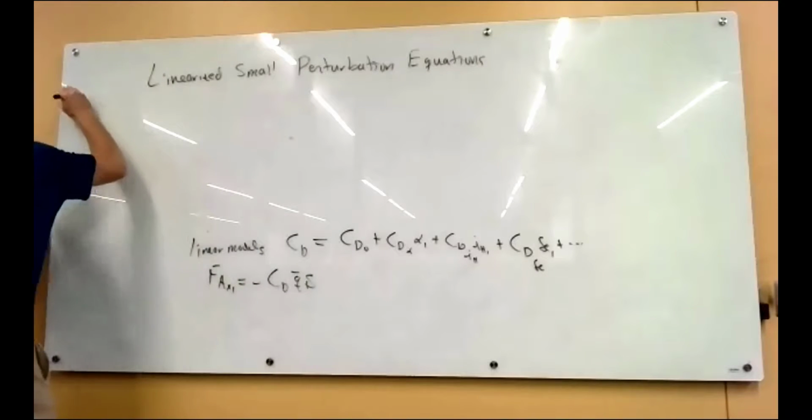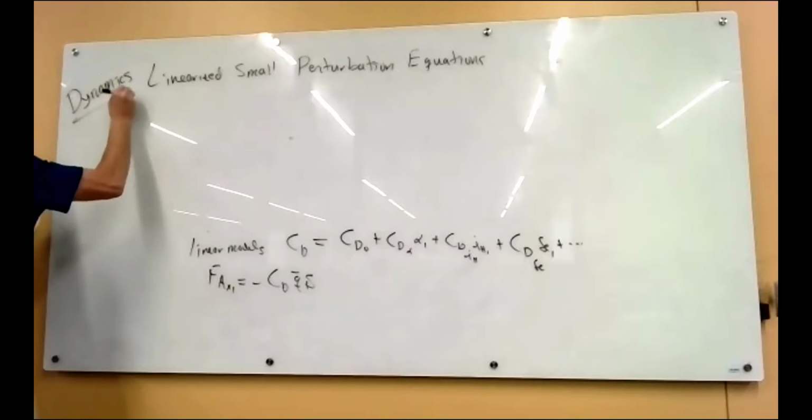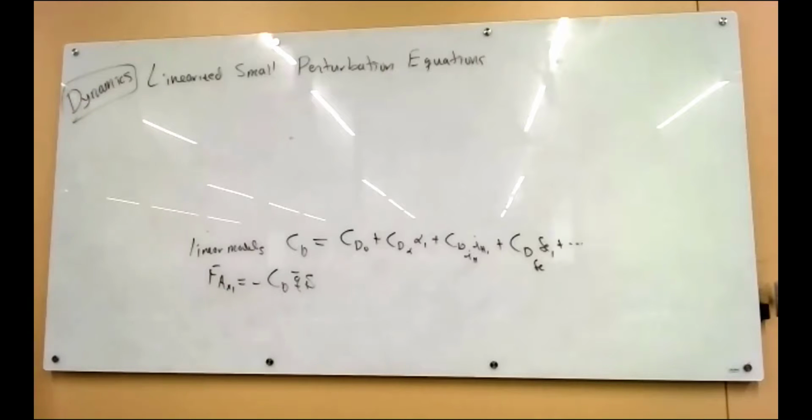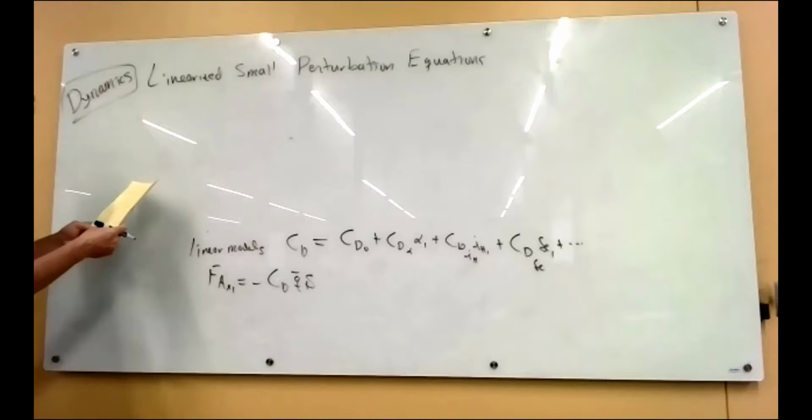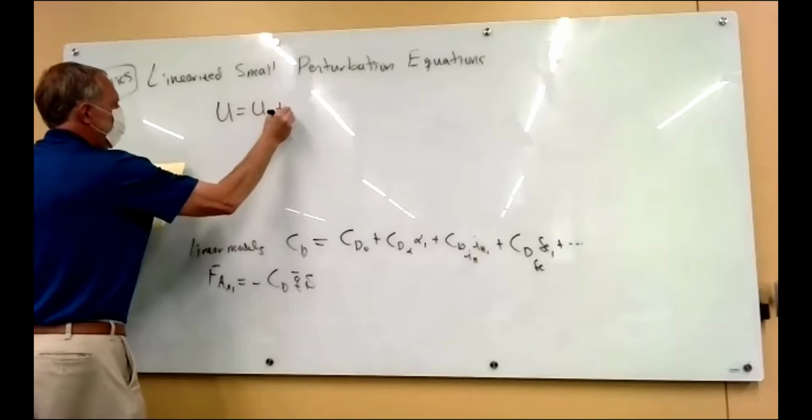And these are dynamic differential equations that we'll eventually solve using Laplace transforms. And again, remember the reason that we do the small perturbation stuff is that we can't solve the nonlinear equations using ordinary differential equation techniques. You have to integrate or do numerical methods. And so we linearized, but we still have differential equations. And we did that via the small perturbation analysis.